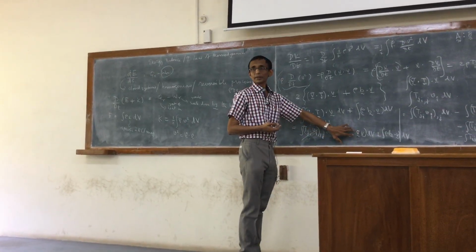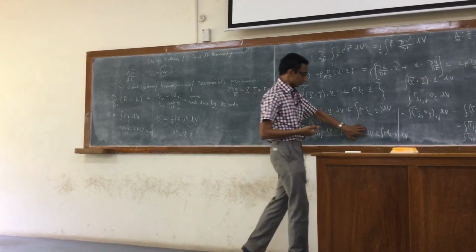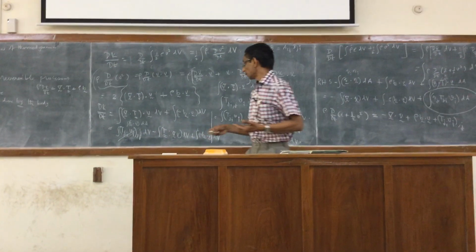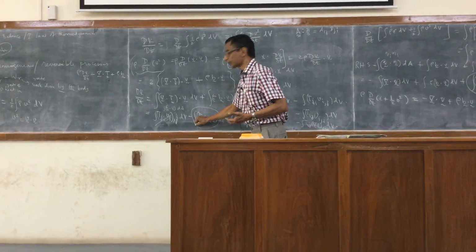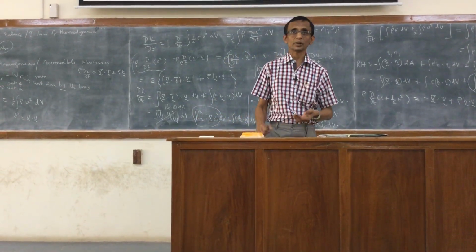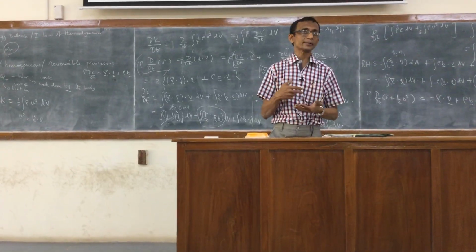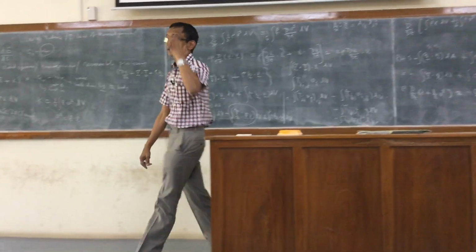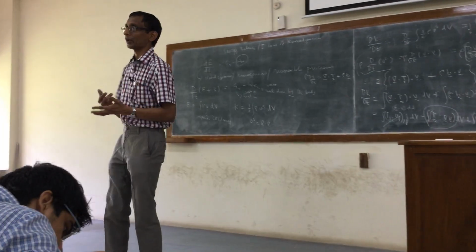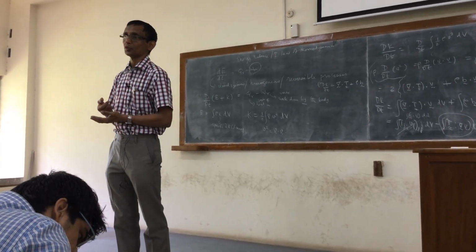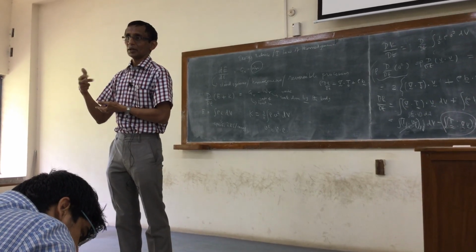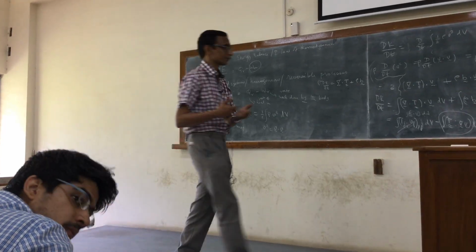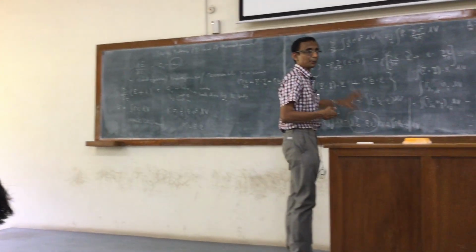This one, there's a negative sign. Of course, this will immediately turn out to be positive. And this is what we can call the term arising out of viscous dissipation. I have to prove actually that this is greater than 0. It will typically turn out to be greater than 0. Then the term will become negative. So because of viscous dissipation, it will lead to a decrease in the kinetic energy. That is the term coming out of viscous dissipation.